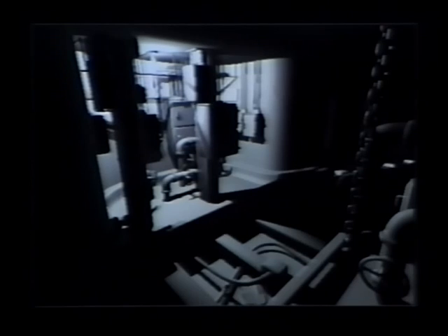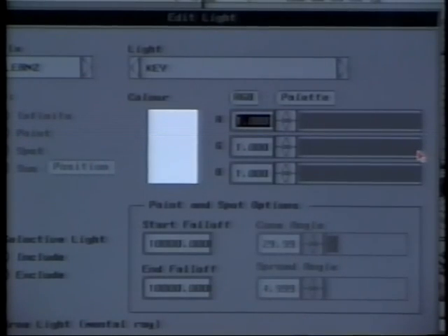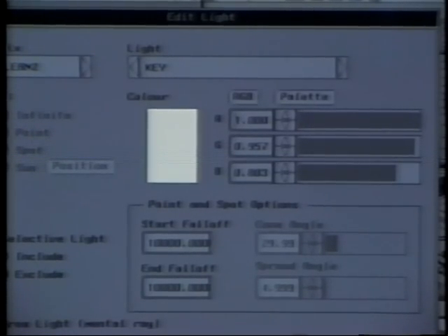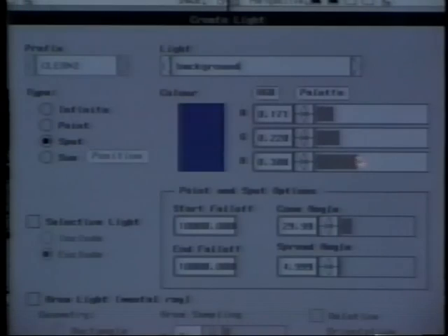We can adjust our lights a little bit and tint them away from white, so I'll give this tungsten light a slightly warmer, yellower color. The quality of your rendering slightly improves when there's some color in your lights, and even just a little bit will help reduce banding artifacts and improve shading. Now our background light will be more boldly colored, as though colored signal lights were used in the tunnel.